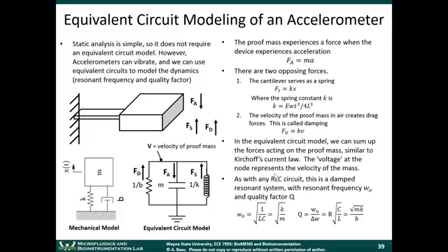In a circuit, you know that we have these things called resonances. In the mechanical system, we also have resonances. With any RLC circuit, the resonant frequency, given in radians per second, is the square root of 1 over LC. And if we plug in the values for L and C, we find that in the mechanical system, the resonant frequency is the square root of K divided by M. So just looking at this, what do you think is going to happen in a mechanical system as we miniaturize it? What will happen to the resonant frequency?